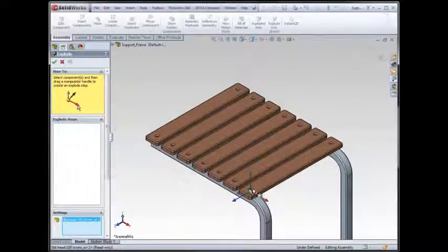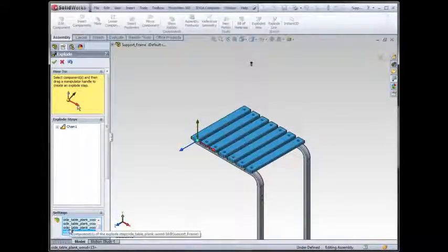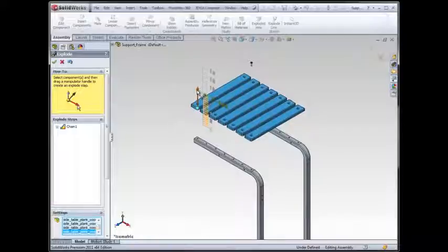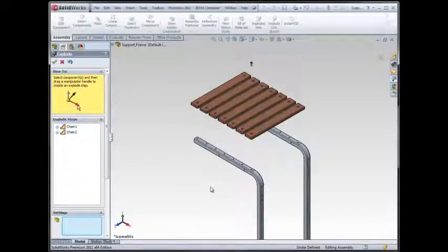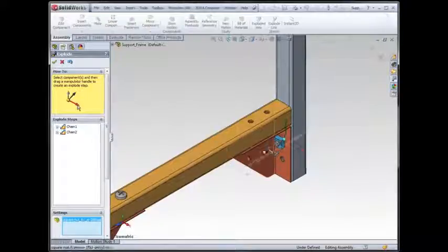I'm going to start by removing this flathead screw and just drag it, and like I said, usually you just kind of eyeball it. You can select multiple items. I'm not even holding down Control, because really what's happening is I'm selecting for this blue box in the Property Manager, and anytime you have a blue box you don't have to hold Control. Move that up a bit. Try to do this in the right order so that it's impressive at the end.